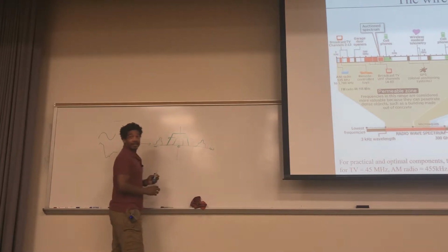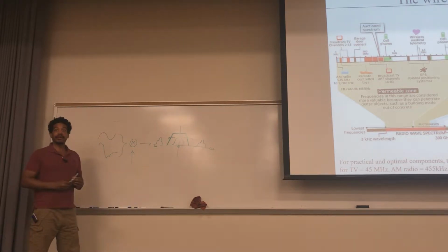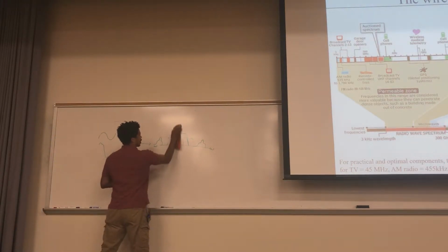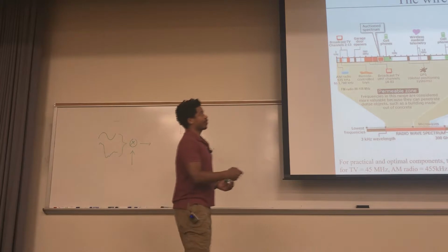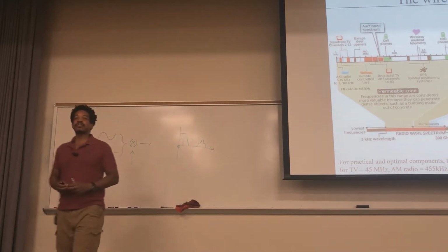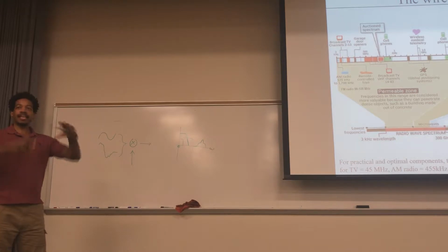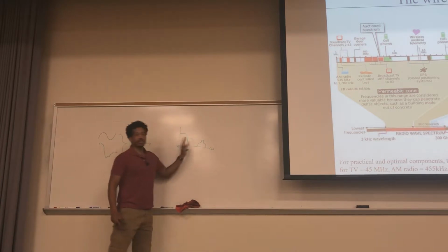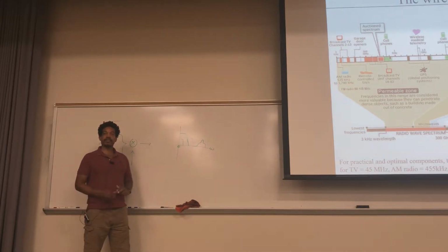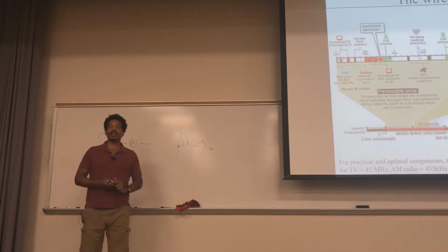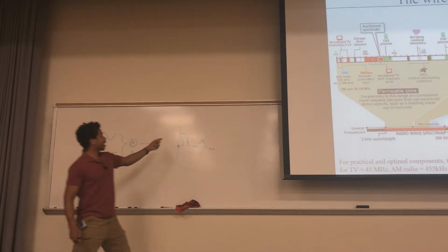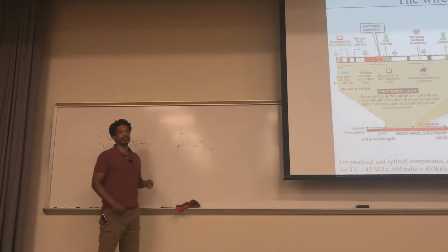Is it like 0 hertz or just 0 frequency? Yeah. So you have a signal at 0 radians per second. If it makes more sense, you can just think of it like this. But for people who make these kinds of devices for RF systems, they think of the entire spectrum. So this is just the frequency spectrum in its positive and negative. The negative side just looks like a mirror copy of the positive side. So that's why this is a low pass, but it looks like a band pass when you mirror it.